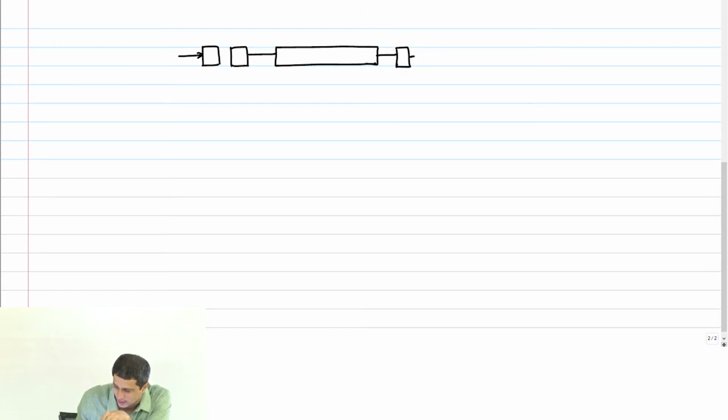So let's now proceed to see how we can make this even faster, right, by exploiting certain design considerations of the flop. If you look at the flop, it's nothing but two latches back to back, right? So this was phi and this was phi bar, or if you want a positive thing, then it should be like this. So latch L1, L2, L1, L2.